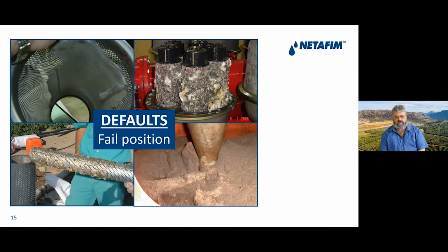At the bottom left, we have the media filter. This one is with a filtration sand. The way that this filter operates, normally we have an inlet with some sort of distribution mechanism to spray the water evenly over the sand at the top. The water will then pass through the sand, and the sand will then collect the dirt particles.